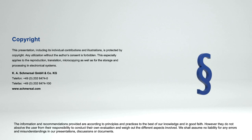That is the entire safety function. So as a function, we're looking at it, that's a guard door interlock function. We went through that decision tree to say it was an S2, F1, P2. Our performance level is D. So we needed to be in a certain performance level for that safety function.